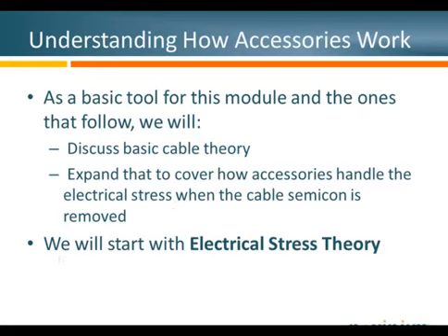So what I'm going to do at the beginning is discuss some basic cable theory and expand that to the accessory theory. Because if you understand the theory of how the cable works, how the accessories work, where the highest electrical stress areas are, then you better understand what's critical in the installation of the accessories and why the cable preparation is critical, and can therefore incorporate those into the design and into the installation to make sure you have a very reliable system.